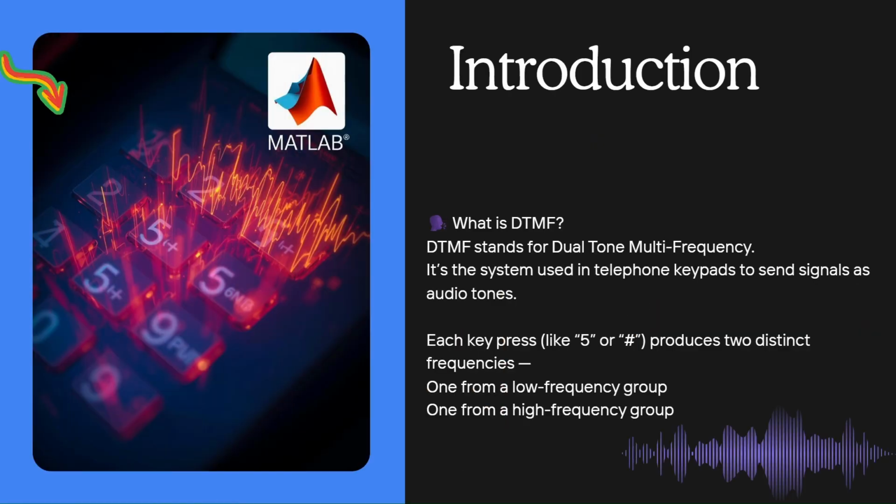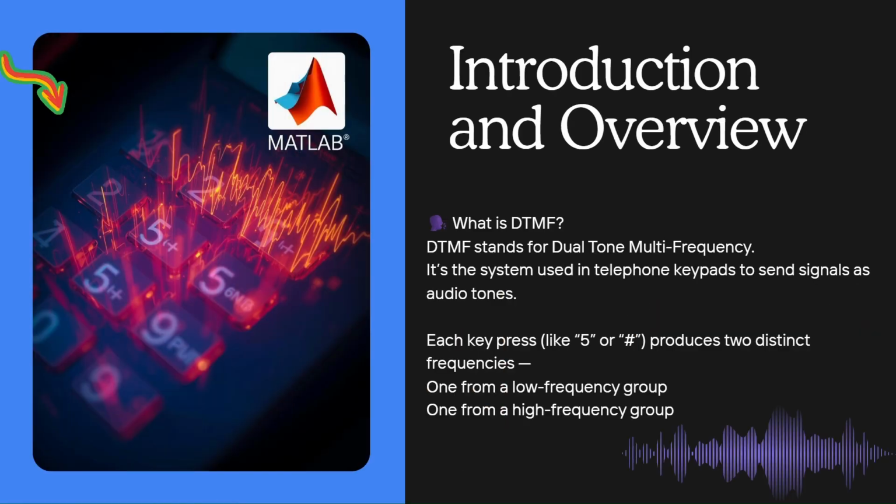Let's begin with a quick introduction to what DTMF actually is. DTMF, or dual tone multi-frequency, is the technology used in traditional telephone keypads to represent the numbers we press as unique audio tones. Every time you press a key on a phone, like 5 or hash, you actually generate two specific frequencies at the same time. One comes from a low frequency group and the other from a high frequency group.